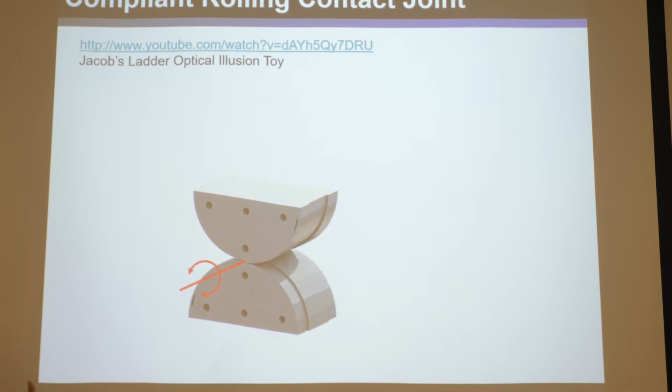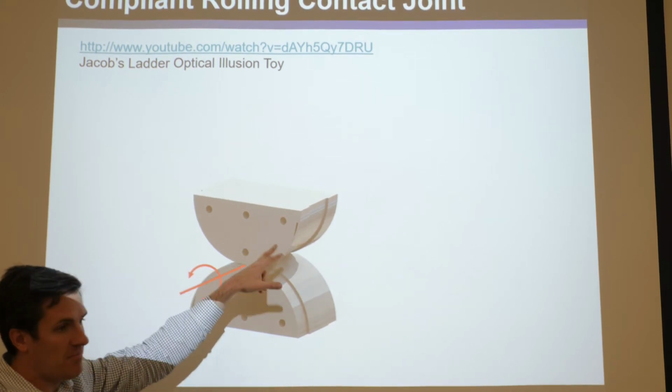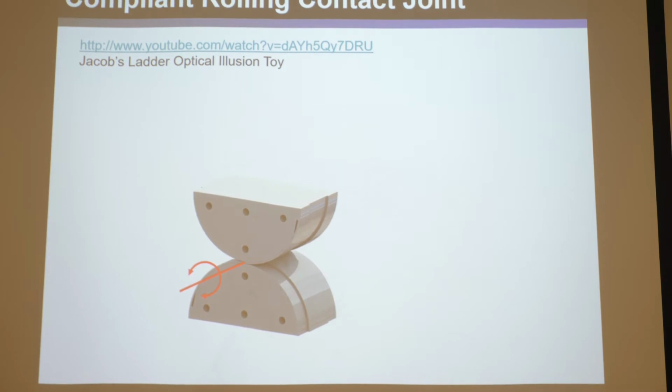It never approaches its yield stress because the curvature on the strap, whether it's wrapped around this drum or that drum, is the same. So over its entire range of deformation, almost 360 degrees, unheard of by a compliant hinge, it doesn't ever increase in stress, so it doesn't break. And it also remains the same strain energy, which means the force to resist it, which is the derivative of the strain energy with respect to the displacement, is essentially zero.